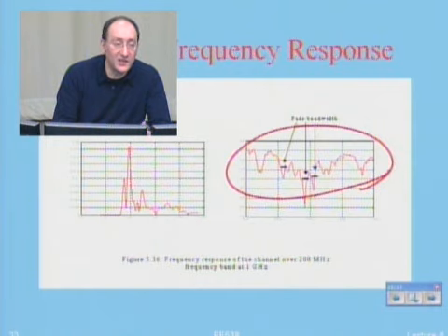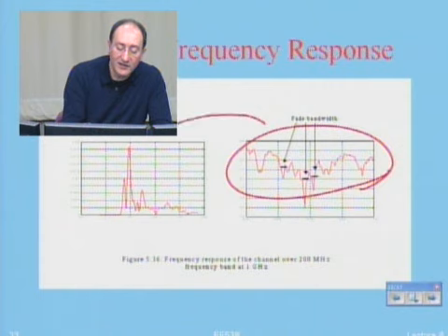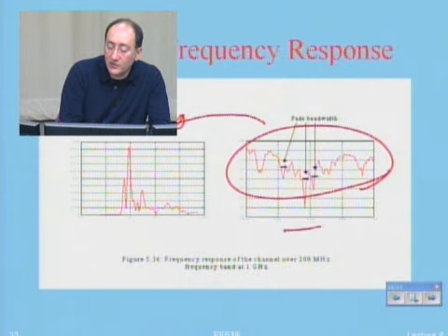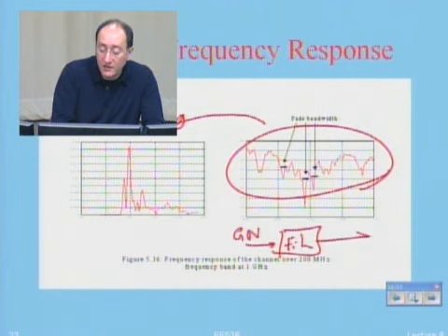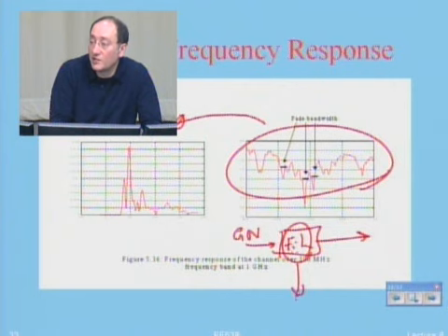And if you go with the spectral estimation techniques, you can model that very similar to a frequency domain measurement system, really. So you can model this to be the output of a filter in frequency domain, which is run with Gaussian noise, and then define the parameters of this filter, which is the location of the poles of the filter.